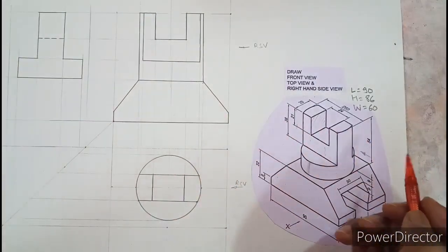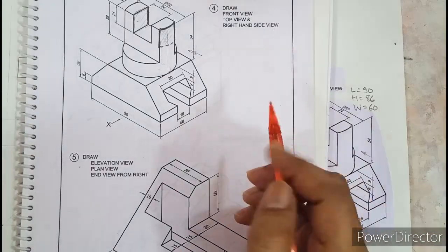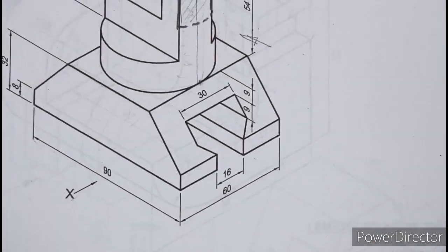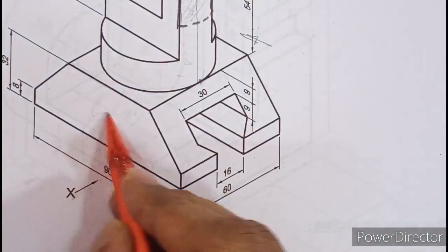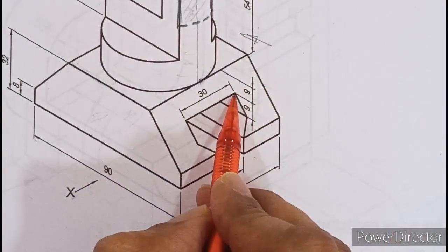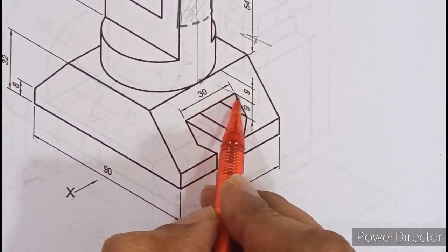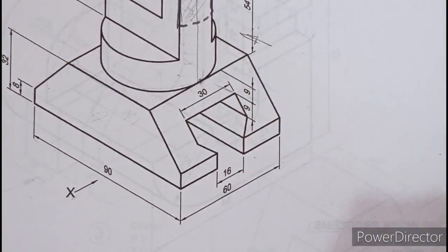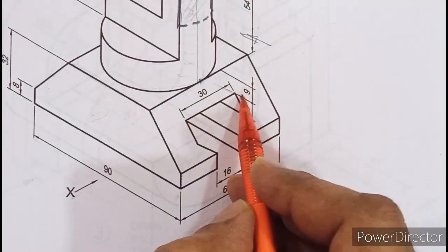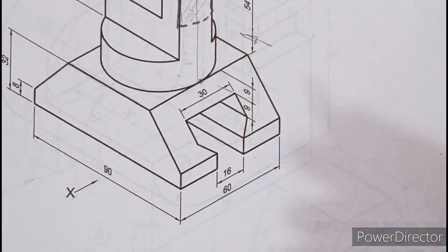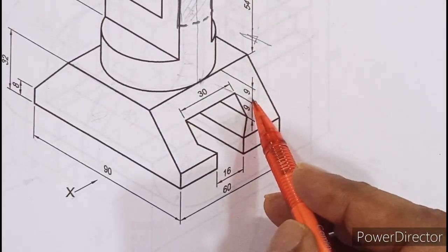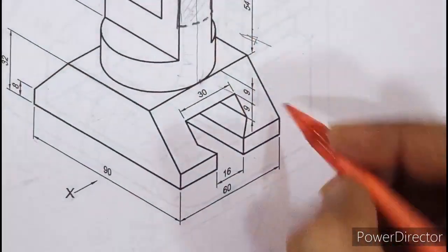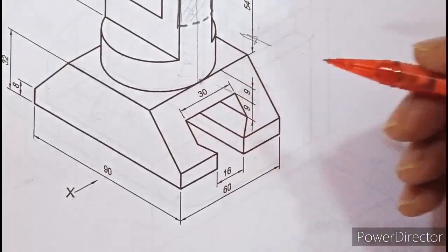Now apart from this platform, as I discussed before, there are a few hidden lines within this platform. Let us see what that is. So if I enlarge a little, when you look in the front direction from here, you cannot see, look at this corner. From this corner there is an edge passing inside. Is this 9 or 6? How to read? For some students it might be 6, some it might be 9. So you have to follow this ISO standard. Dimension is always shown above the line. So this side is above. So you have to read it like this, it is 9. So this dimension is 9 actually.